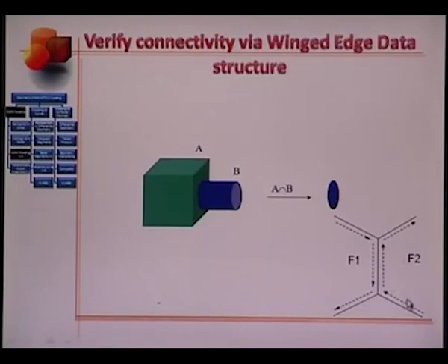Now if you recall, for any valid solid, polyhedral or non-polyhedral, with different surface patches constituting the solid and different surface patches stitched at the common boundaries, a valid solid will be one for which each boundary edge will have not more and not less than 2 faces incident to it.